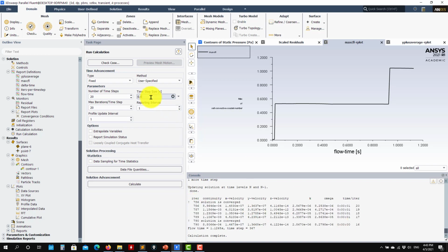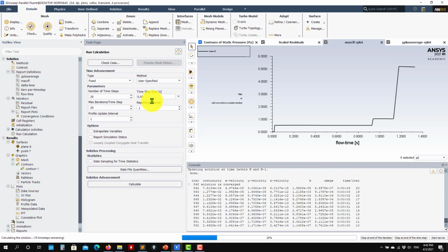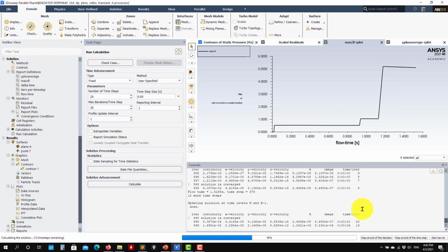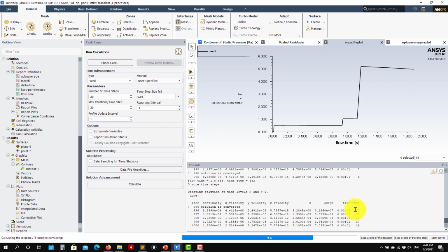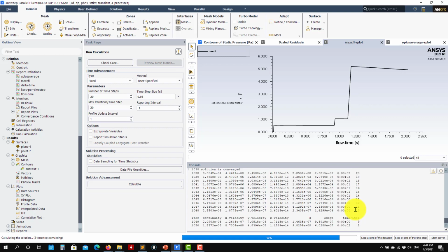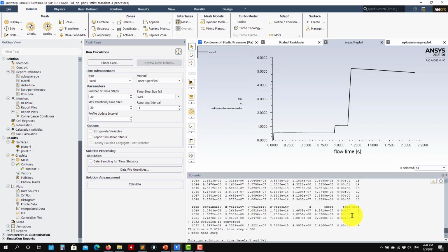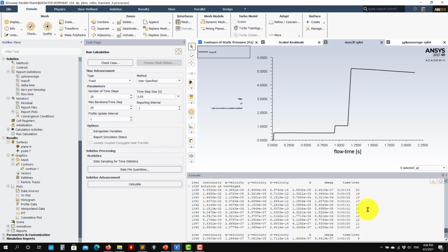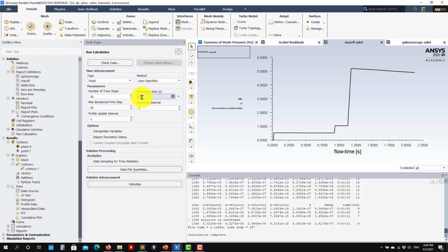So for instance, see that if I go here and increase to 0.5, my CFL number is much larger, I will converge much faster, but now it's taking about 14 iterations to converge. Still, this is okay, but something ideal would give you a good compromise between computing time and number of iterations. It's something that will converge in about 5 iterations here. Okay, so let me leave it here at 0.1, and at this point we found our time step.